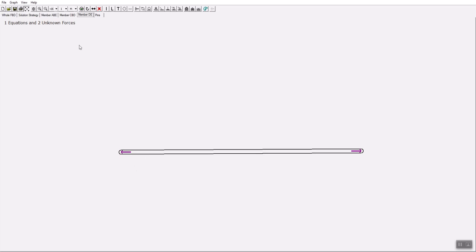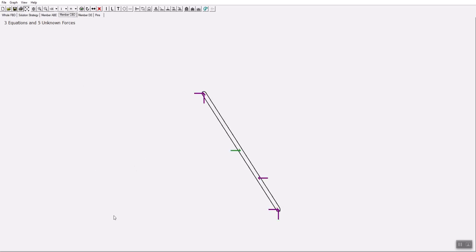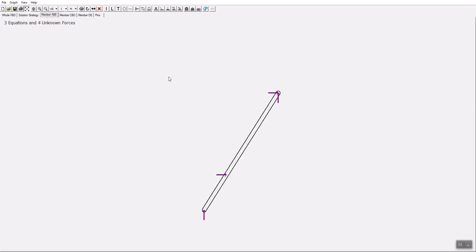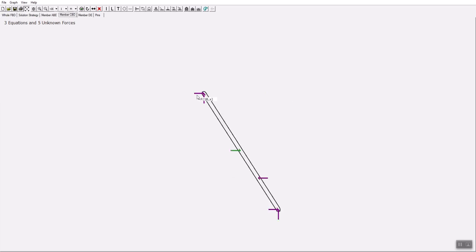And then we go to the right member. This force from the horizontal member is known. These 2 forces, F1bx and F1by, actually are known from here, Obx and Oby, because this force pair and this force pair are connected by Newton's third law.